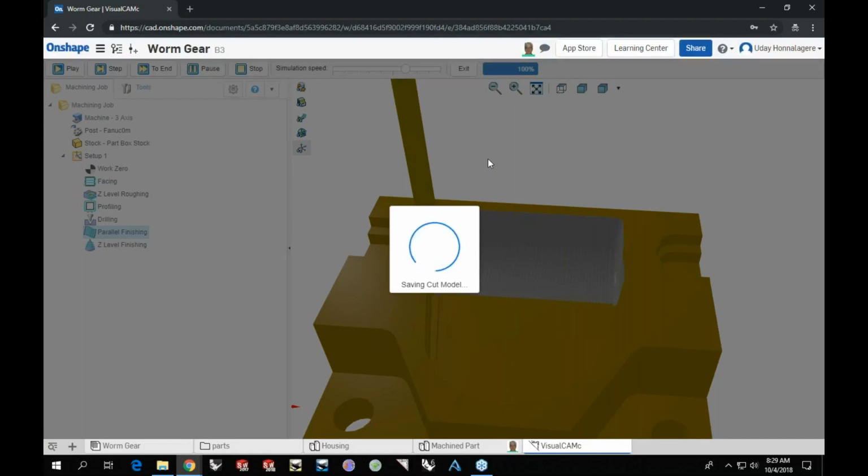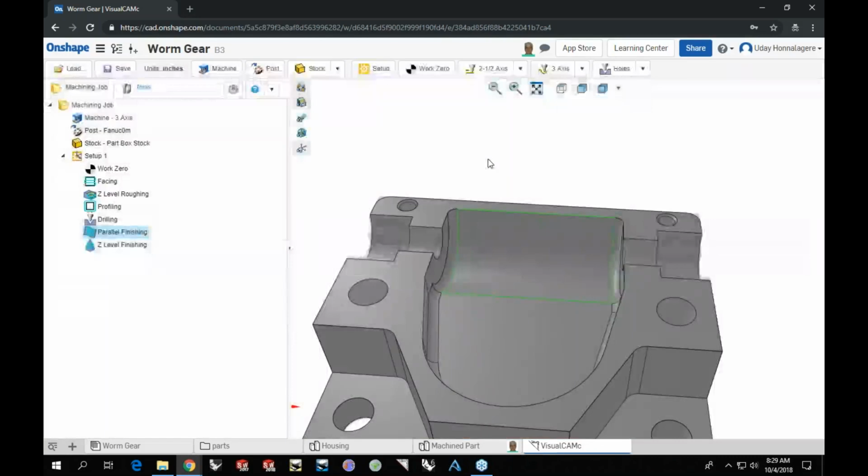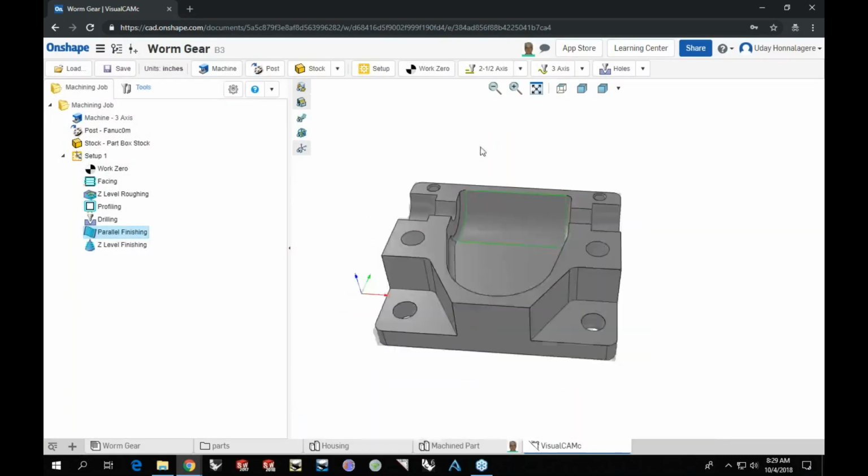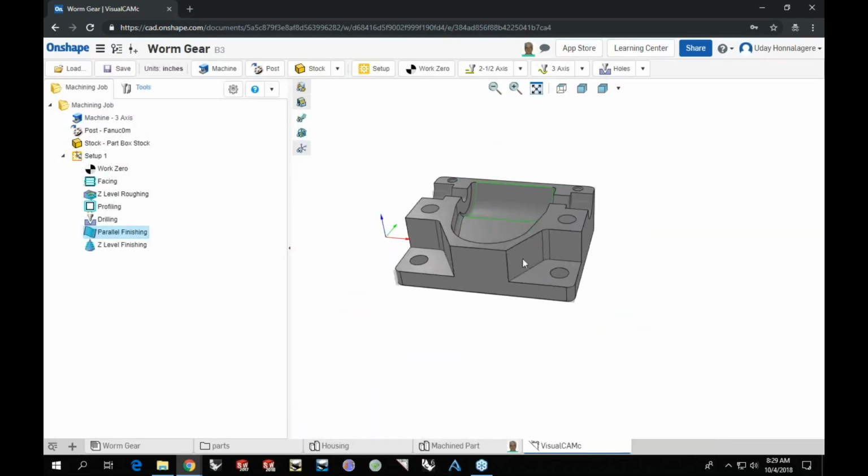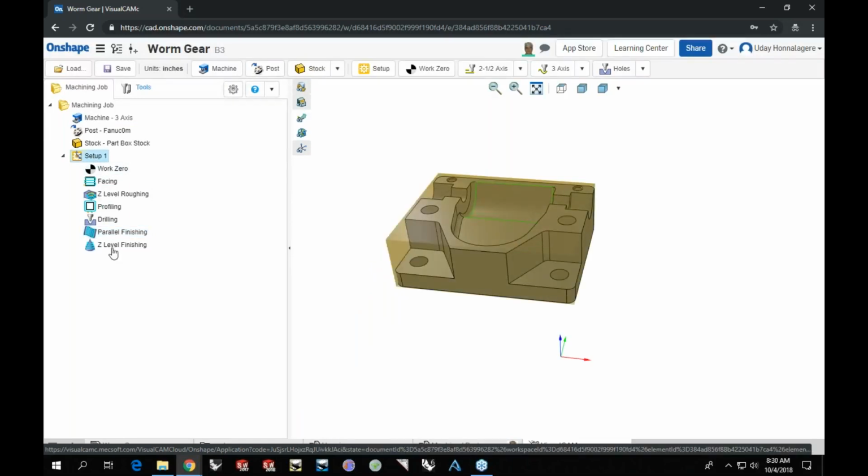Now once you have all these toolpaths and operations programmed, the final step is we need to communicate this to your machine tool. So we do that by a process called post-processing. And like we've already selected a post processor at the start of your programming workflow in here, we can post it out to the machine tool. So you can either select the entire setup to post process all of the operations in the sequence in which you program, or you can post individual operations as well.